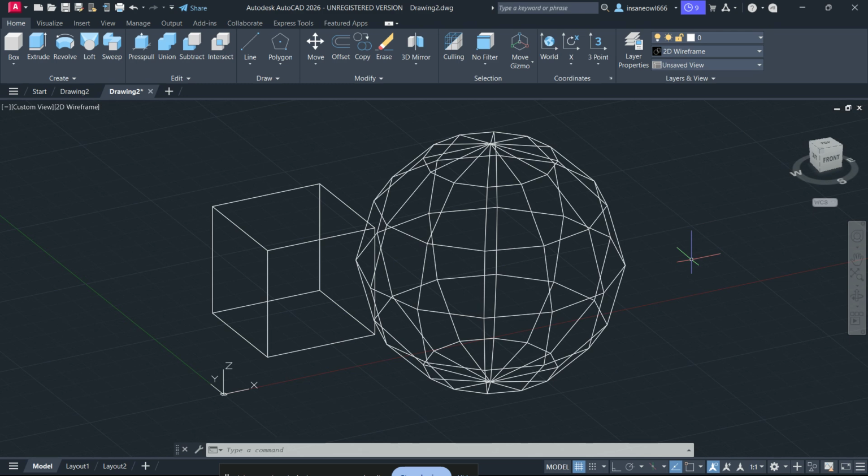If you are still stuck, try combining these methods. For example, micro-move the object first, then clean the body, then test the Boolean operation on a smaller group, and if needed, scale the model up before trying again. In many cases, one small change is enough to resolve the error. The key is to remember that 97022 is usually not a random crash. It is AutoCAD telling you that the solid geometry has become too complicated, too close, or too irregular for the Boolean engine to solve cleanly. So the solution is usually to simplify, separate, clean, or slightly adjust the geometry until the engine can process it.